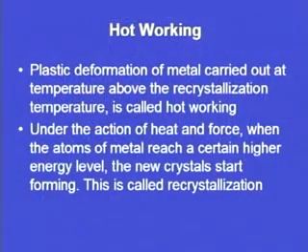So, hot working, what is basically hot working? It is plastic deformation of metal carried out at a temperature above the recrystallization temperature. The important point to mention here is that we are working on the metal at an elevated temperature. The limit of that temperature is the recrystallization temperature, and whenever we are working above it, we will call that metal forming operation a hot working operation.